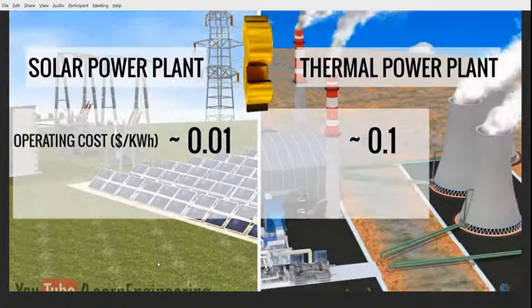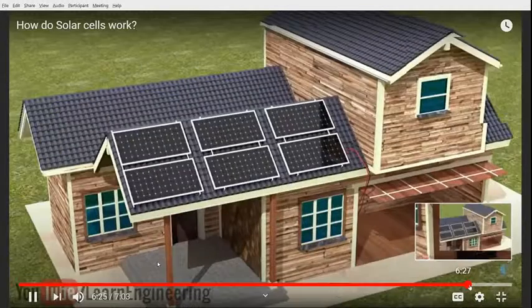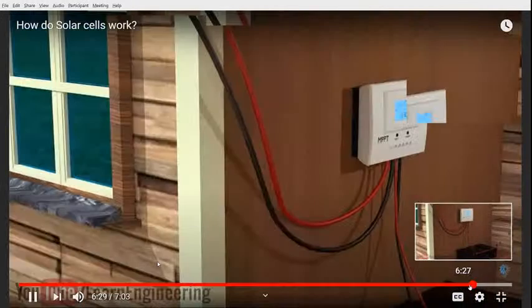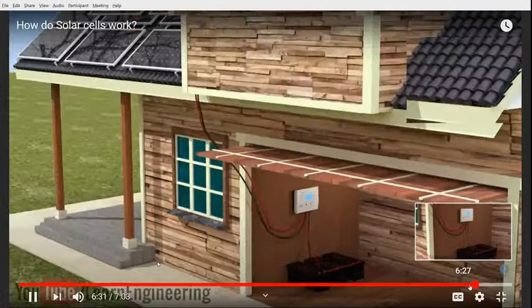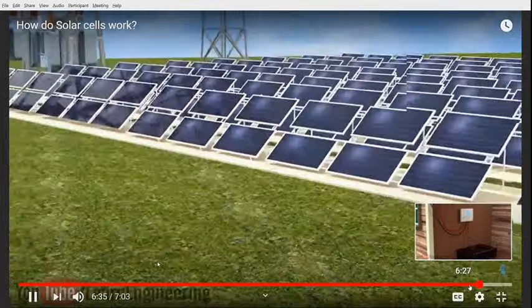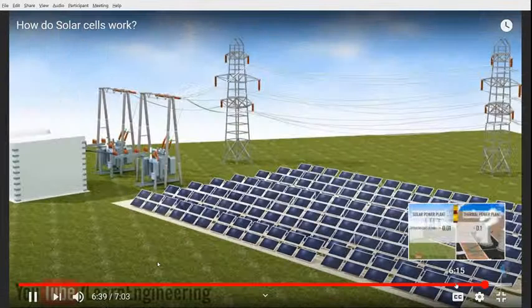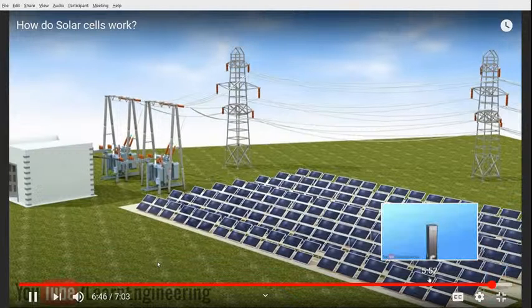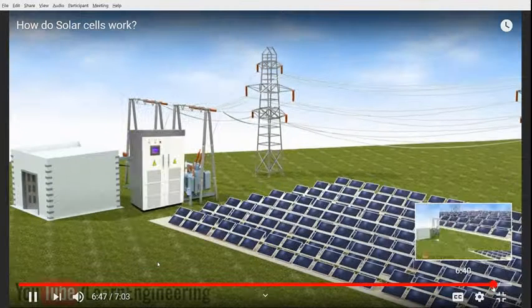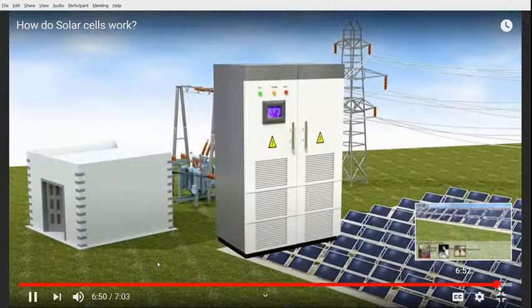Solar panels in residential homes have the option to store electricity with the help of batteries and supercharge controllers. However, in the case of a solar power plant, the massive amount of storage required is not possible. So, generally, they are connected to the electrical grid system in the same way that other conventional power plant outlets are connected. With the help of power inverters, DC is converted to AC and fed to the grid.